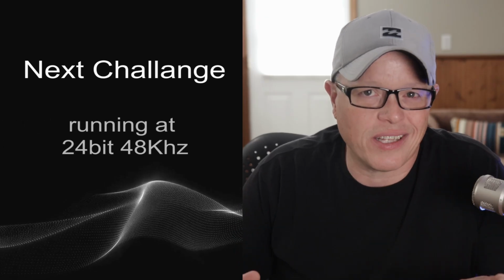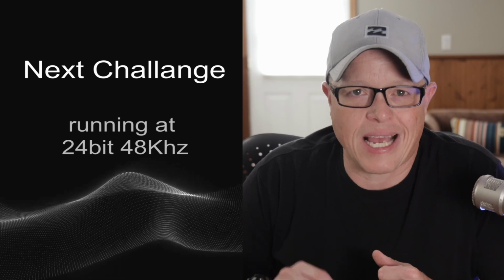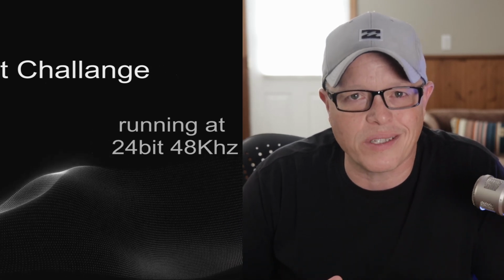And the next challenge, we had a big decision to make. The Allen and Heath Avantis sound console is capable of 24-bit 96 kHz audio sample rates. Unfortunately, bringing the QSC Q-SYS core into the mix via Dante meant we had to run the entire system at 24-bit 48. Now, I'm hoping that someday QSC Q-SYS will take it up to 96, but for now, we have to actually step down in quality to have it in our signal path.